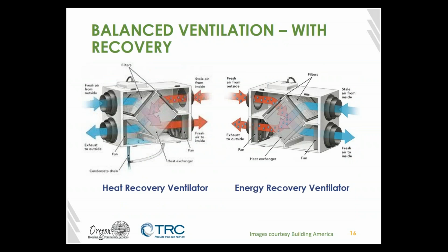So a quick little difference between heat recovery and energy recovery. You'll often see them spoken in the same breath or typed with just a slash between them because they essentially do the same thing. Heat recovery lets you take the energy of one stream and convert it to the other. So in the winter, let's say, because that's the predominant need in Oregon, you've got your nice, warm, cozy air on the inside, you're pushing it out of your apartment, and it's being replaced by super cold air from the outside.